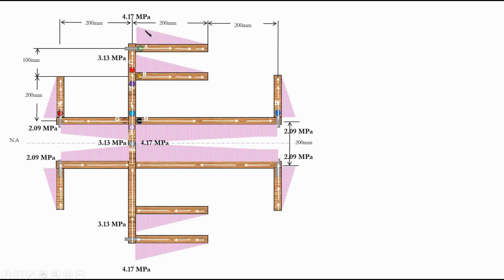For each of these segments, each will represent a force. You could say that the stress value for this segment multiplied by the area of the segment will give us the force for the segment. How does this force look? It looks something like that. So we can represent these flows, because what is flow? Flow is force, or shear force in this case, per unit length. So force is equal to this stress multiplied by this area. The same concept behind that.